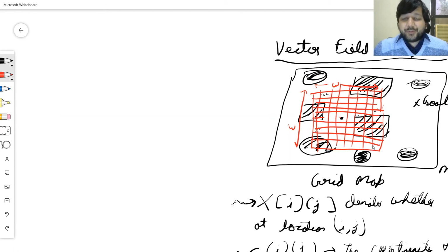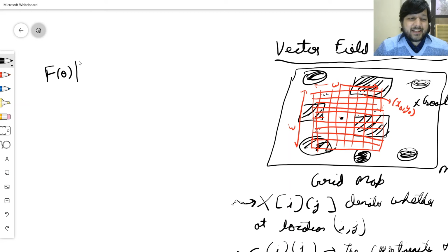And it's not a beautiful black and white picture, it is something else. So let's take any general X0, Y0. It may be an obstacle or it may not be an obstacle. So C(X0, Y0) is the confidence that this is an obstacle or not, and I'm going to use the same repulsive force formula. So the repulsive force applied due to an obstacle O, and I only consider its magnitude, not the direction.